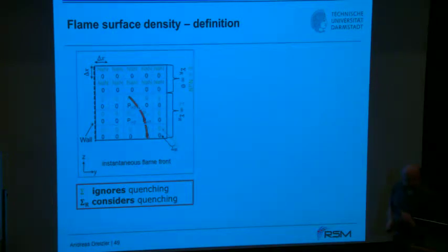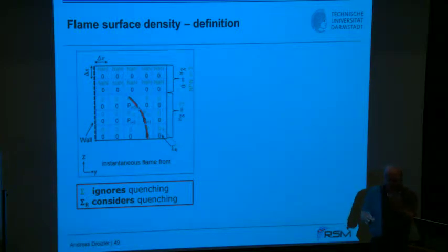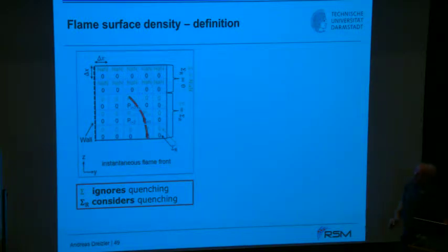First of all, the flame surface density, in reality, is a surface in a volume. We have only 2D OH PLIF, that's why we can look only in this projection for the length of the flame front in a unit surface. And this unit surface has been parametrically varied. In our case, at the end, it was 250 microns.